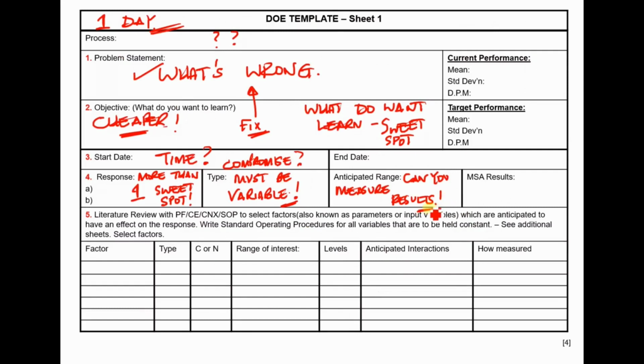And therefore what you might have is a jig here to measure the results in a very small window, because that's all production is trying to achieve. But during the DOE, what we're trying to do is to push the process around. I want the process to go to wild places so that I learn how I made that happen, and then I can learn how to hit targets. So you need to just check, if I'm going to go to extreme results, do I have lots of capability on my measuring equipment to just measure all the extreme results?